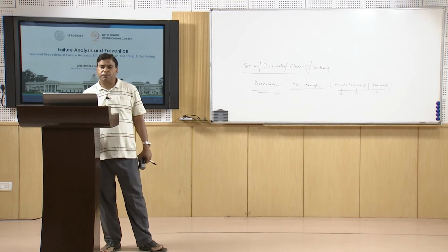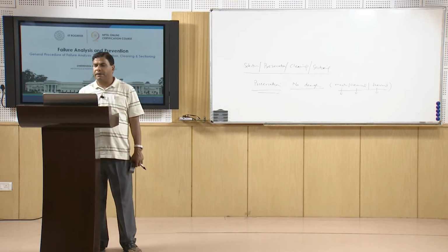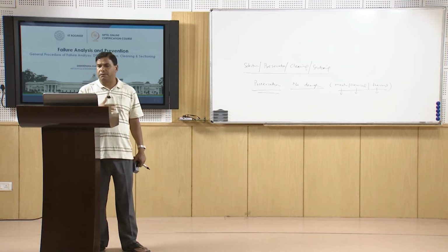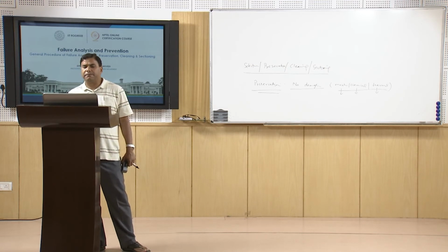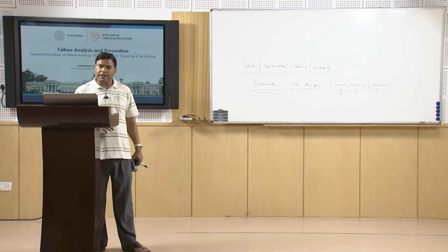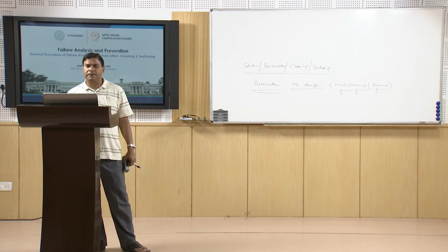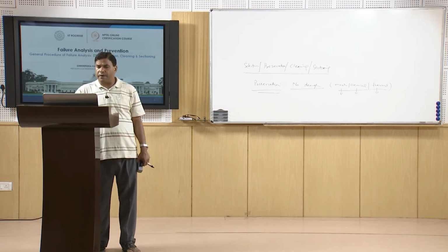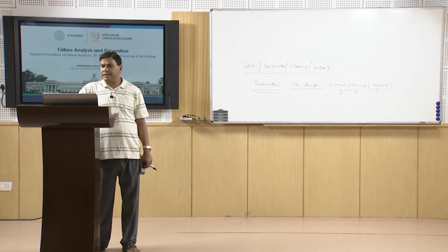There is also the possibility that seawater or fire extinguishing fluid is present, and then this must be removed if required, and for that purpose it is cleaned with acetone or alcohol, and thereafter the fracture surfaces of the failed component should be washed and then kept in a dry place. So, the best is to dry the fracture surface with a compressed air jet and then place it in a desiccator.